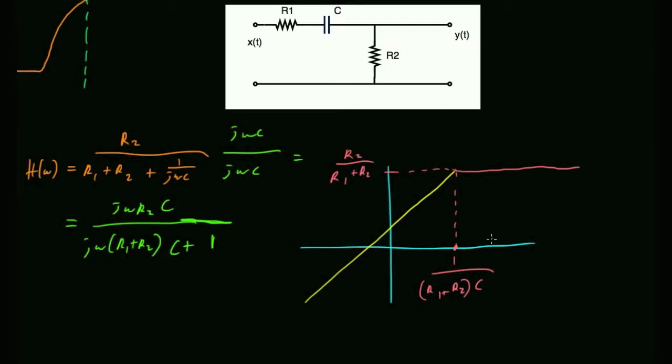So controls is like, let's say you've got a system, like an incubator that you want to keep at a certain temperature. You send a control signal to set the thermostat, and obviously if it's too hot, you want to turn the thermostat off, and if it's too cold, you want to turn it on. But the thing you're trying to heat has a time delay. It takes some time to heat up and some time to cool off. So there's this whole delay element involved. It's almost like a filter.